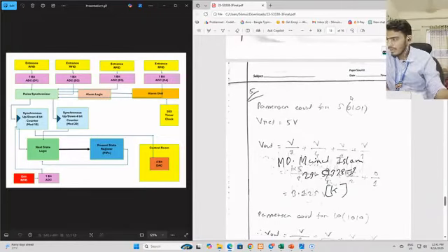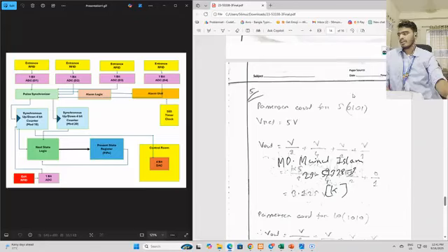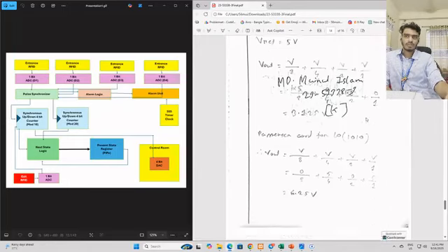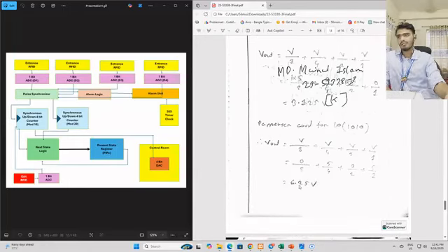And at the 5th point, we have been asked to show how the DAC output voltage represents the passenger count for 5 and 10 passengers. We assume a 4-bit DAC and a V reference of 5 volts. So if we use a 4-bit DAC, the V out equation goes like that, and we get 3.125 volts for the passenger count 5, and for the passenger count 10 we get 6.25 volts output from this digital to analog converter, and the V reference is definitely 5 volts.